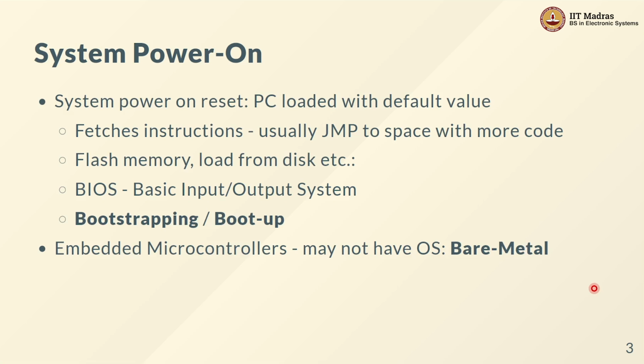It essentially says that there are storage elements present inside your circuit. Those are, of course, our flip-flops. It could be some memory blocks, but primarily we are interested in the flip-flops. And to be more specific, we are primarily interested in those flip-flops which hold information related to the state of the system. Now, what do I mean by that? After all, isn't every flip-flop holding something related to the state of the system?